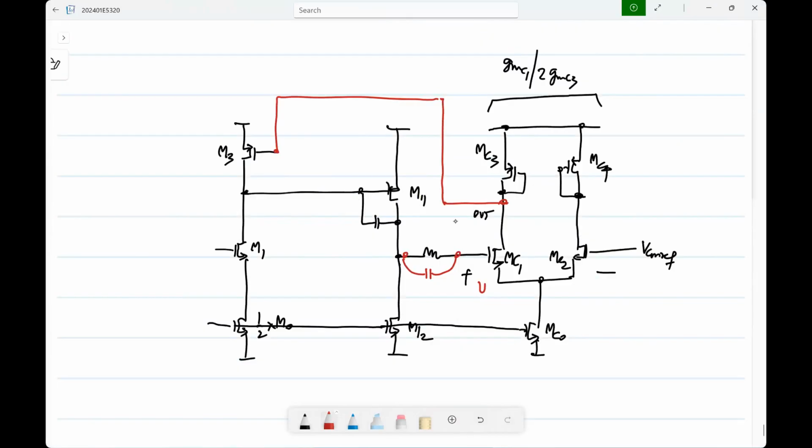Okay. So in some ways this is more efficient, but it's always more messy to have a single common mode feedback loop around multiple stages, because you will always end up with more poles and zeros. So if you can use individual common mode feedback circuits, but let's say you're really being stingy about bias currents and all these things. You want to really squeeze down the power. Then maybe you can use this, because after all, this needs only one error amplifier stage for the entire op-amp.